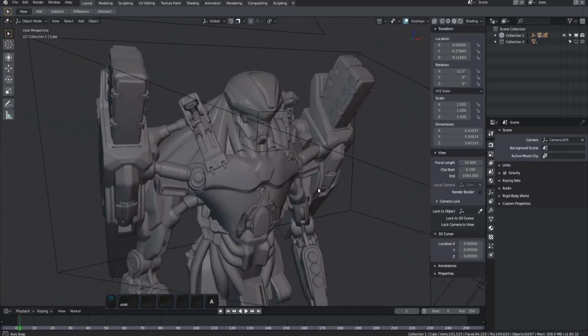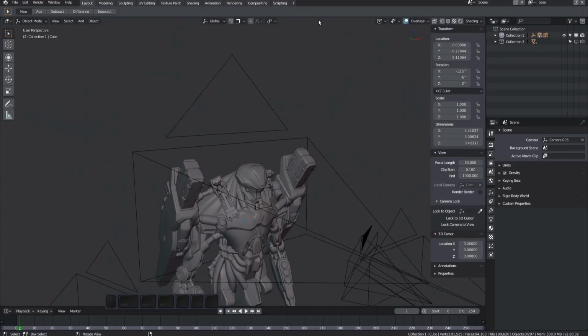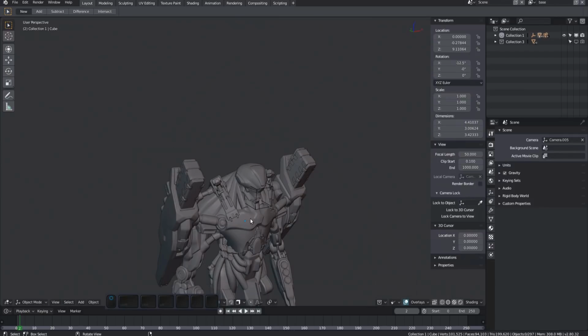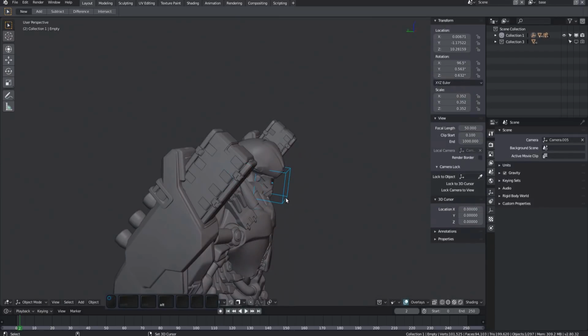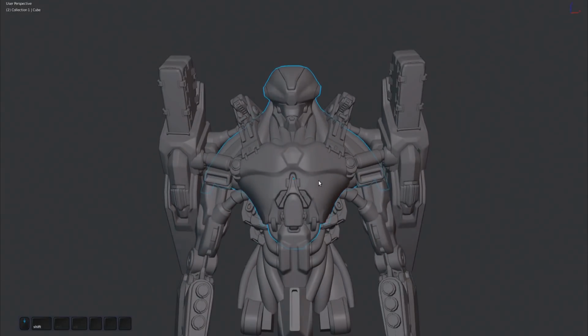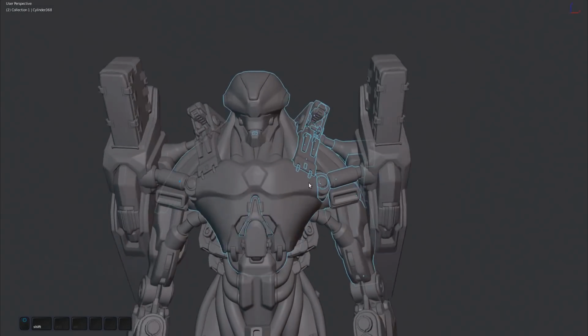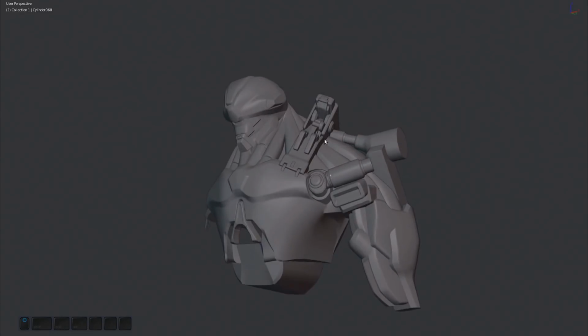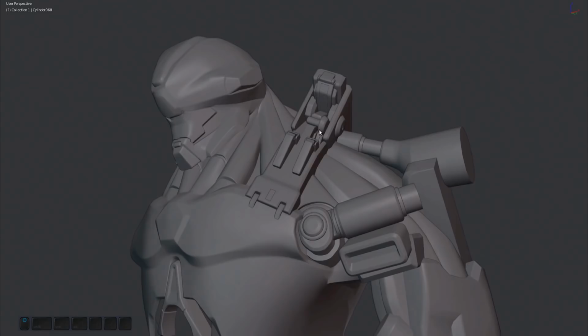The focus tool is used to isolate specific objects. I have Blender's view selected, mapped to the F key, so focus is mapped to Ctrl F accordingly. Make a selection of objects and run the tool. Everything but those objects will be hidden. In addition, mirror modifiers will be toggled off, if any are found, so you can focus on the originals.